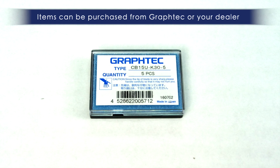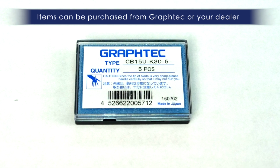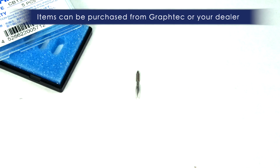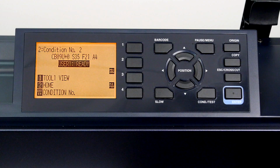Keep in mind that these larger blades require a new blade holder. The CB15U K30 blade is better suited for more pliable medias such as sandblast mask, since it can maneuver more easily around corners due to its sharper angle. This in turn provides clean corners. The first step is to configure a condition specifically to cut sandblast mask using the CB15U K30.